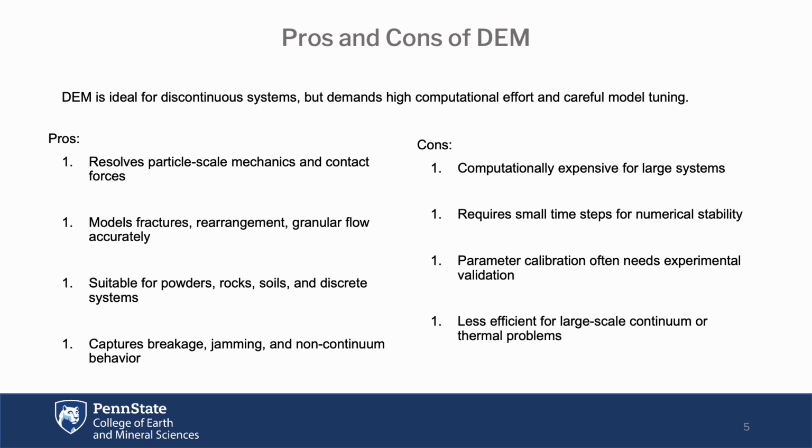However, these capabilities come with significant computational costs. Since DEM typically uses explicit time-stepping and resolves every contact at each time increment, simulations can be extremely expensive, especially for systems with thousands or millions of particles. The time step is constrained by the material stiffness and mass, often in the microsecond range.